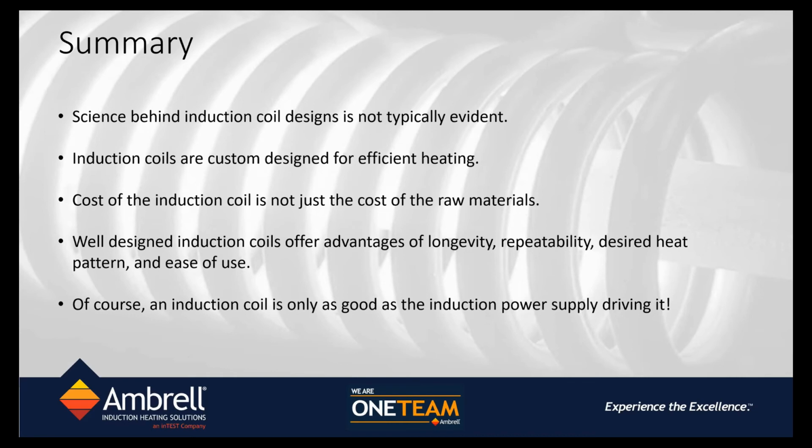So in an induction heating coil, obviously the biggest power loss is the distance between the coil and the part. The farther the coil is from the part, the harder it has to work to deliver the energy. In some cases, the heat from the hot part comes into the cooling water of the induction heating coil. So that affects the heat loss from the part. So those are the cases where we would employ insulation between the hot part and the coil, but try to make the coil still as tight as possible, because that's what gives us the most efficient coil design.